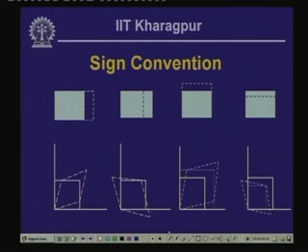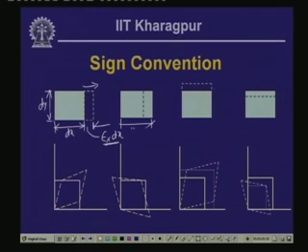So, let us look into the figures. In these figures, let us say this is a small element of length dx at a point where the member is undergoing strain. This is the extension, and if the strain in this direction is epsilon x, we write this as epsilon x dx. This is elongation, and we call this a positive strain. Again in this element, this is dx and this is dy. Here the compression of this element is denoted by this dotted line, and this is again epsilon x dx, but it has gone in the opposite direction, or compressed. So here epsilon x is negative.